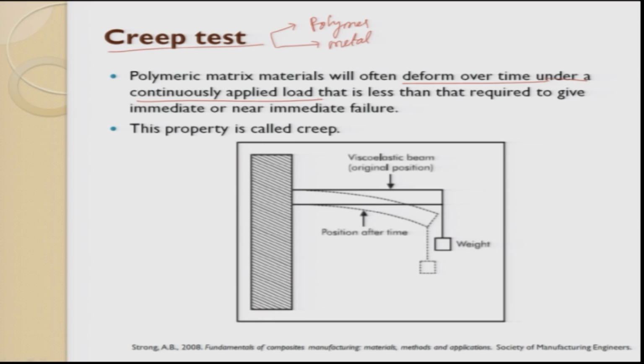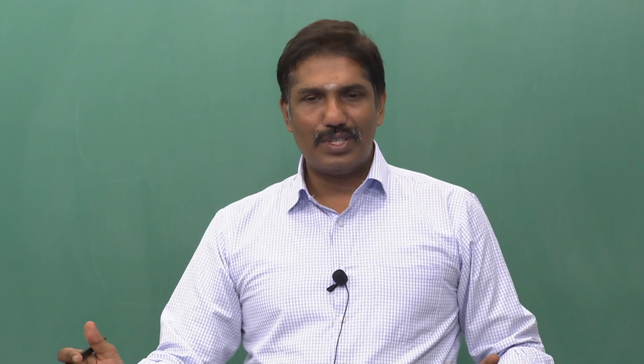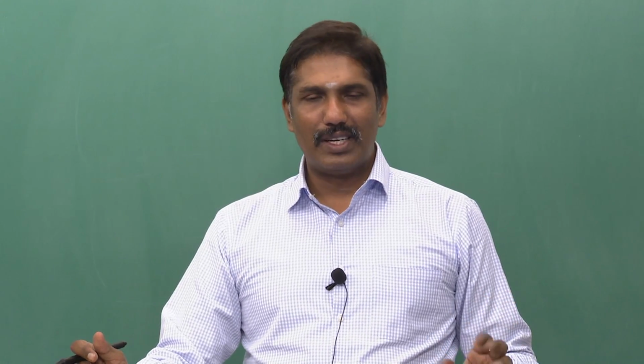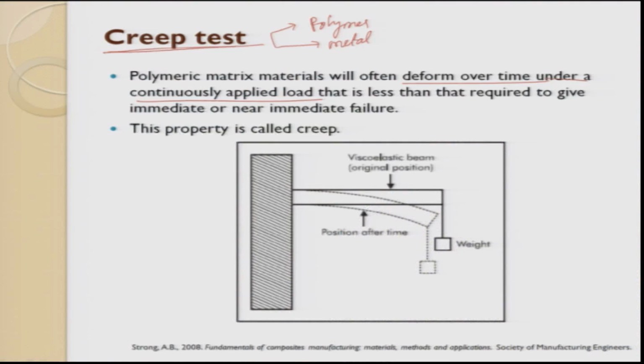A pot will be attached with a thread and that will be attached to a hook. All of a sudden the pot falls down and gets shattered. Why? Because the polymer undergoes expansion. So this property is very important when you try to hang a load for a longer period of time. So this test will try to reveal the values which can be used for applications.